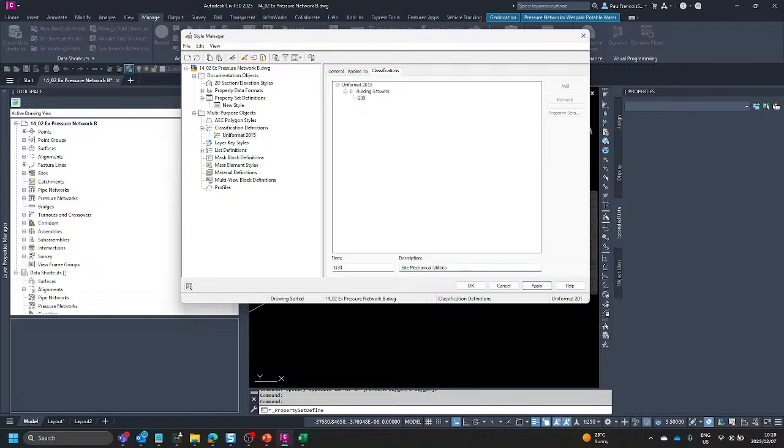Thankfully you don't have to do this for every drawing. Once you've set it up once, that will be sufficient. I've even seen that you could delve into Dynamo, I haven't done so yet, to read and write information onto the standard. So if you have an Excel spreadsheet like I have, in theory, using Dynamo, you'd be able to open the spreadsheet, read the information, and write it into the coding.